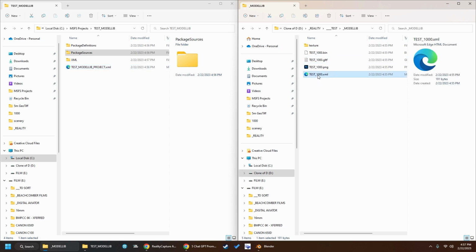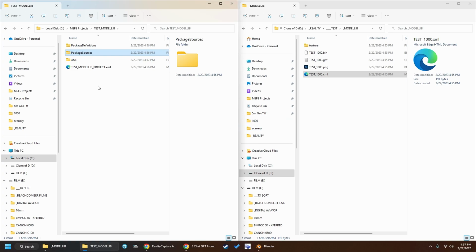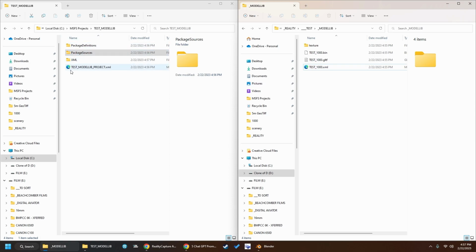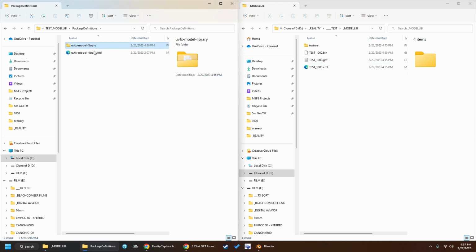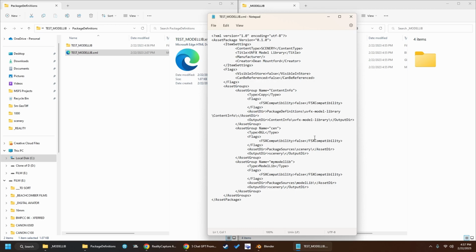So what I'm going to do, the XML, first of all, I'm just going to copy this in here, because if I accidentally nuke anything when I'm working on stuff, then I can always bring the XML, which has a GUID code, or GID code. Not GUID, as some people say. So then I want to highlight these. I'm going to rename them as the model library, and I want to go into the XML here, and I want to change the reference for, here's the version of it.